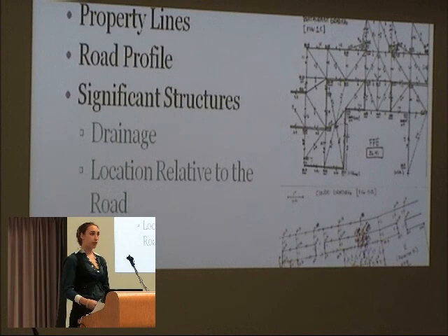The lowest point of the road directly in front of this area is about 16 feet. I had to allow enough distance between the condo buildings and the edge of the road to grade the parking lot at a 2 to 5% maximum slope, ideally as flat as possible, and still have enough room between the edge of the parking lot and the edge of the road to grade down at no more than a 3 to 1 slope so this area could still get mowed and further design would not become necessary, such as a retaining wall or a revetment wall.